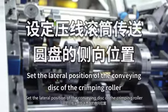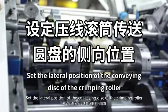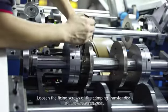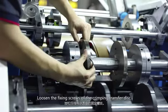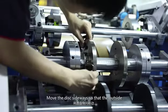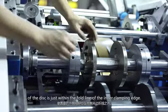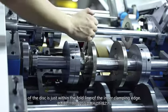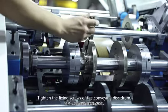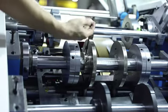Set the lateral position of the conveying disc of the crimping roller. Loosen the fixing screws of the crimping transfer disc. Move the disc sideways so that the outside of the disc is just within the fold line of the inner clamping edge. Tighten the fixing screws of the conveying disc drum.